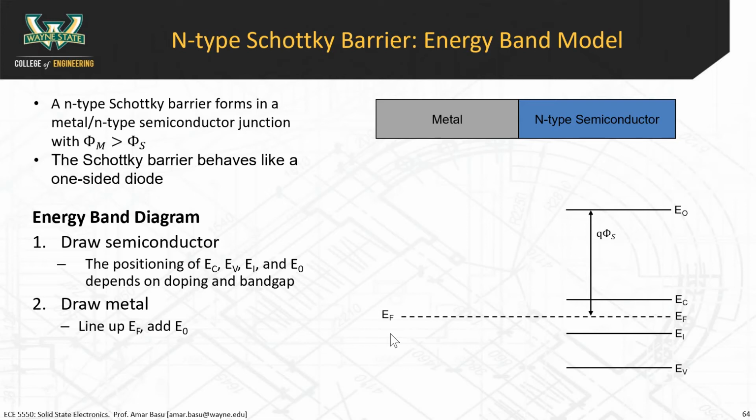What's the rule with the Fermi level in energy band diagrams? It should be horizontal. Under which conditions? Yep. Equilibrium. You got it. At equilibrium, the Fermi level is a flat horizontal line. When you apply voltage to the system, the Fermi levels are going to be different, right? Whichever side has a positive voltage has a lower Fermi level. Remember that. At equilibrium, though, there's no voltage being applied, so the Fermi levels are all going to be at the same energy. Okay, so flat horizontal line.